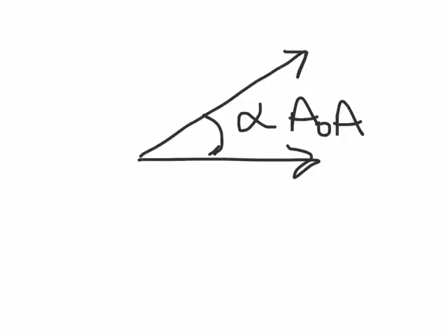You also see pitching moments. So if we pull back on the control stick, this is going to cause the elevator to move upward, and the downward force on the tail is what's going to result. So if we draw an airplane here with an aileron, and let's call this my stick, and I'm going to pull back on the stick, so now I have this.